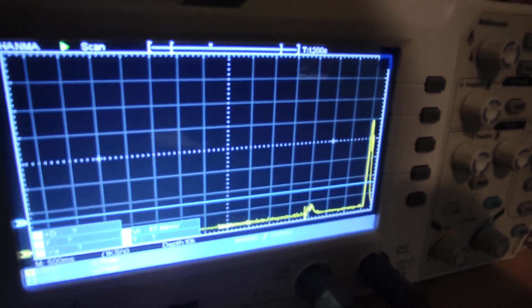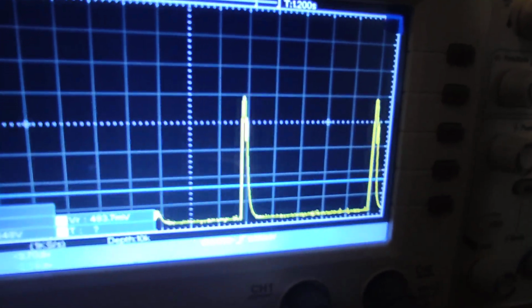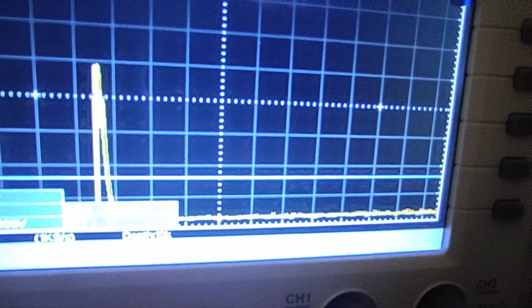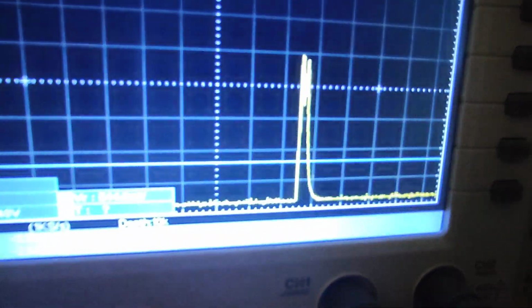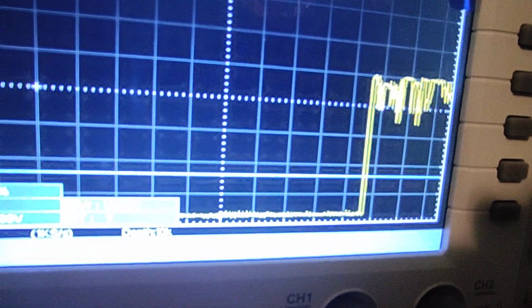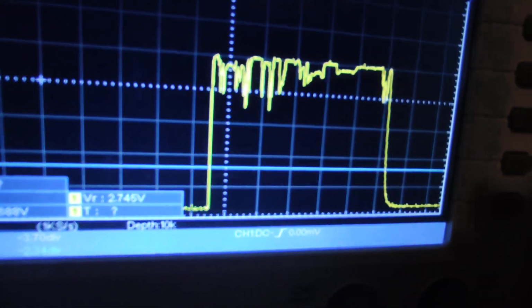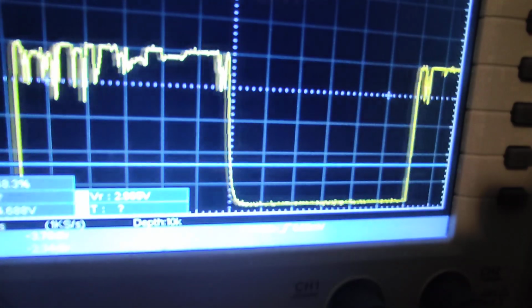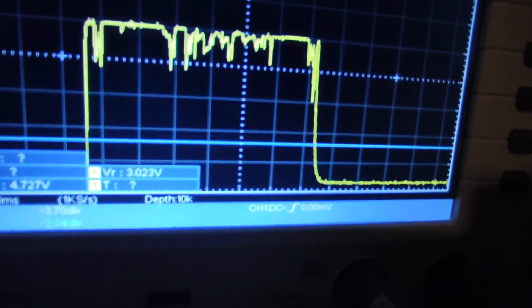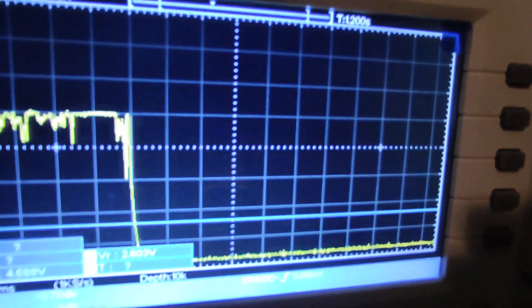Okay, so I put my low pass filter exactly here, and let's read the output voltage. So as you can see, if I press very, very fast, there is not any more square wave, because now it is filtered by the low pass filter, and if I press correctly, you will have a less noisy waveform, exactly as you expected. Now this is just a random value of a low pass filter, but all the noise that was there before is at least a bit filtered.